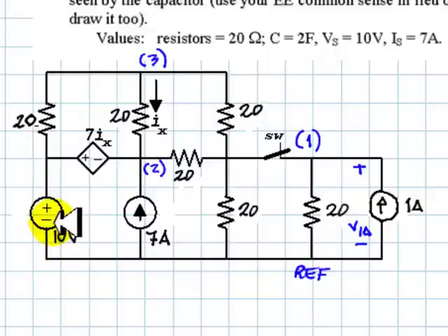But in this case, I'm going to take advantage of this V source, in which I am not interested in finding the current. I would say, well, this is the reference. The voltage source is 10 volts. The voltage in this node is already known, 10 volts. I'm going to write 10 volts there. I will not compute this evil current.